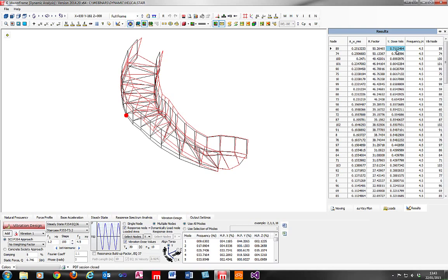The vibration dose value has a different acceptability criteria. Table 5.4 in P354 gives acceptable ranges of the vibration dose value. So for example, it doesn't actually have one for stairs, but it's saying for buildings for a 16-hour day, you're looking for a range of 0.2 to 0.4 for no adverse comment. For something called adverse comment possible as a category, it says 0.4 to 0.8.